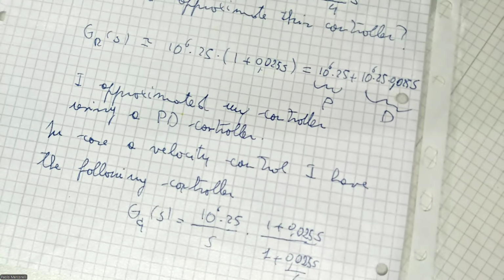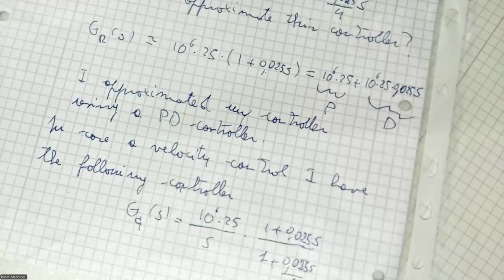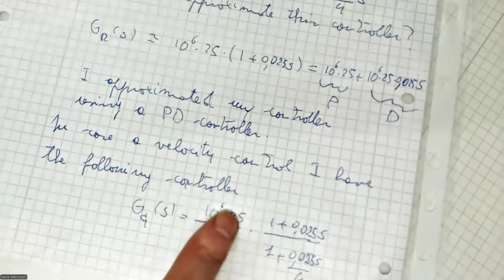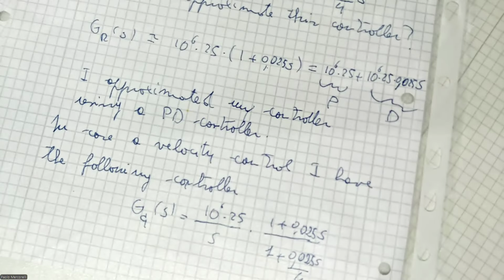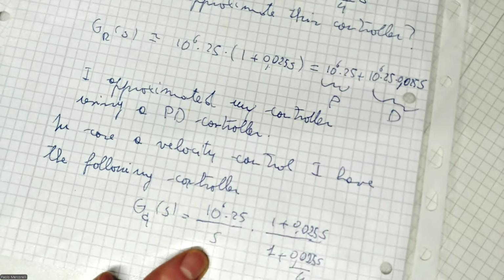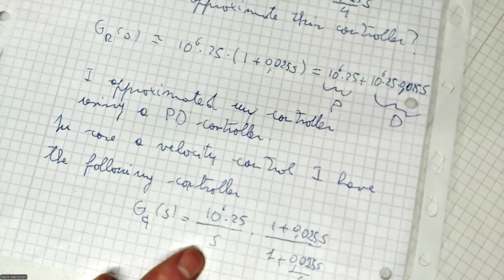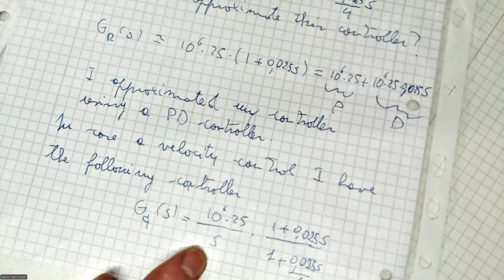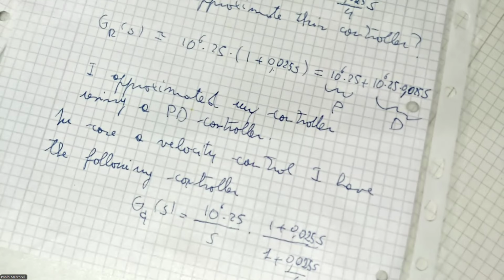Now, I hope to show you, but it's intuitive. If the specification is 1 meter per second in 1 second, chi I is the same. If the specification is to achieve the goal without oscillation in the velocity, S equals 0, I will obtain the same, but in order to obtain the error equals 0, I need an integral, because I don't have in the loop the integral, which maintains for a constant goal a steady state error of 0.